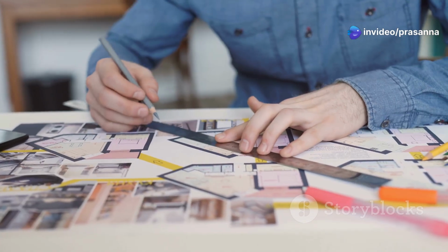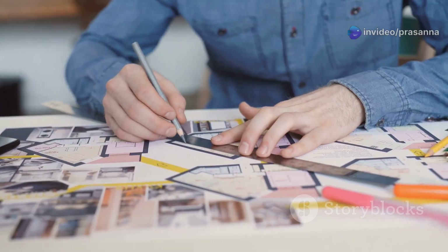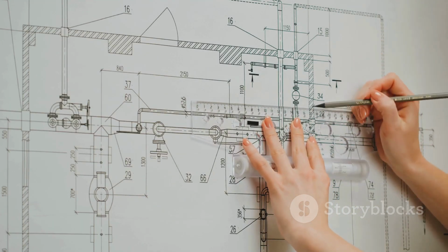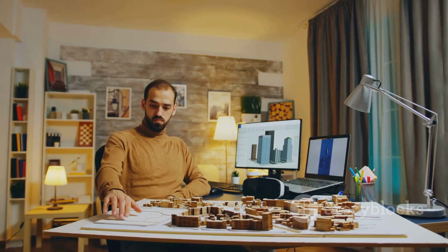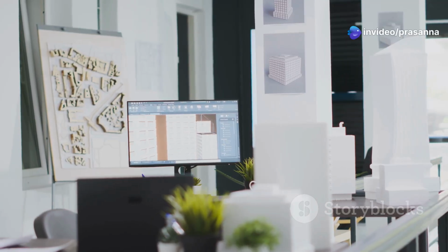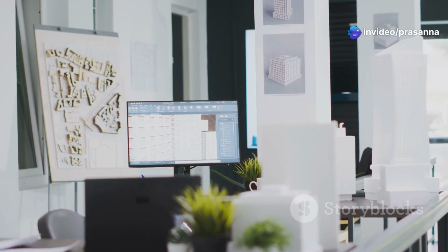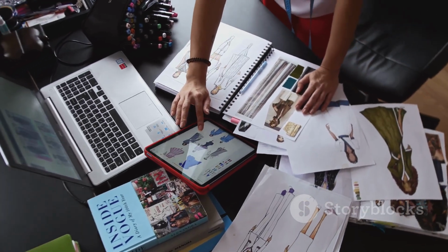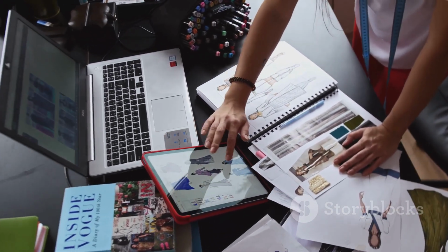In Layout, you can create standard architectural drawings. These include floor plans, elevations, sections, and details. You set up different views of your 3D model in SketchUp. For example, a top-down view for a floor plan, or a side view for an elevation. These views, called scenes in SketchUp, are then imported into Layout.